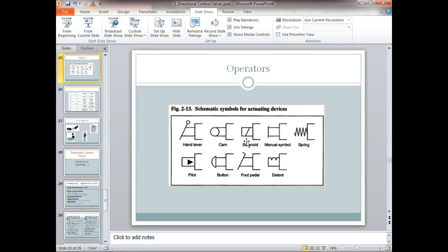And these are some solenoid operated valves. These are hydraulic valves, by the way. You can actually see the ports on the bottom, which is pretty good. Can't see the spool, so these are the solenoid connections on each side. Now, most solenoid valves, as the symbol shows, have a manual override. So we have the ability to push in on this little brass end, and it gives us the ability to shift the spool manually.